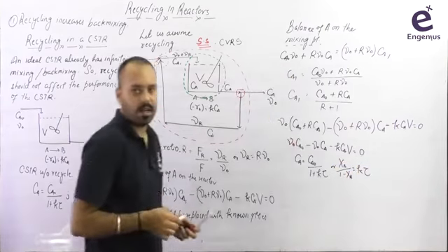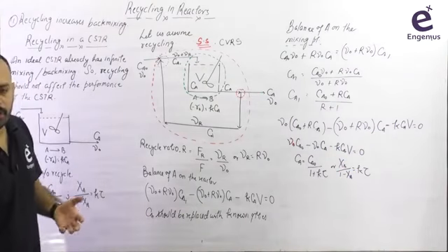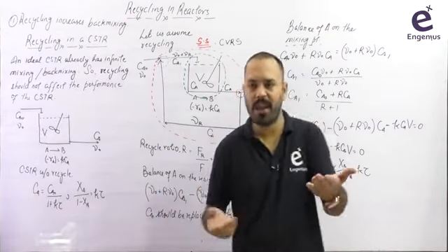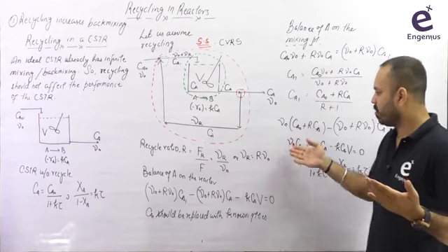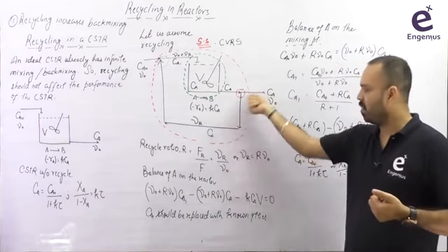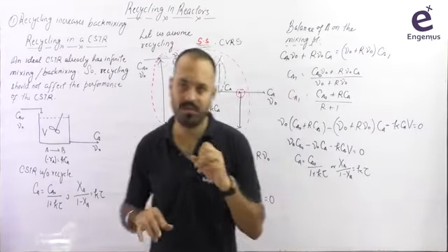Fine. So what is the conclusion from this mathematical derivation? The conclusion is the same, which I am writing here: in a CSTR, whether you have no recycle, without recycle, what is the recycle ratio? What was the recycle ratio? The flow rate of the stream divided by the flow rate of the stream which is leaving the overall system. So if there was no recycle, the recycle ratio value is 0.